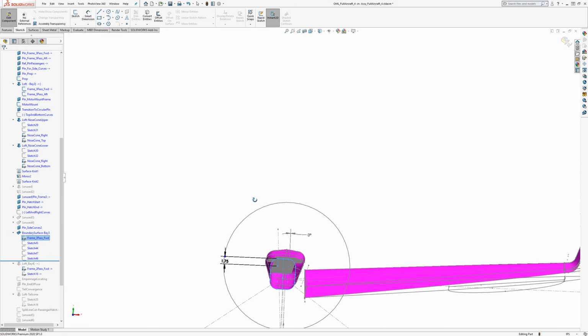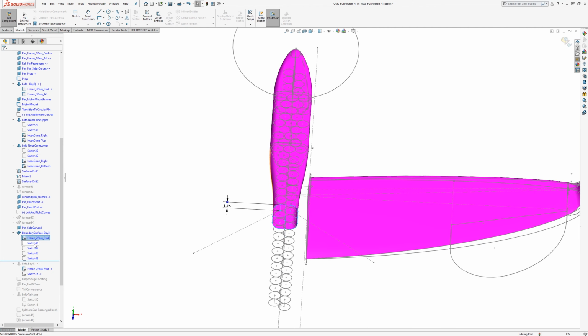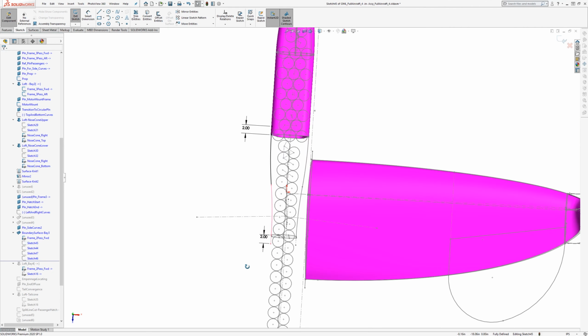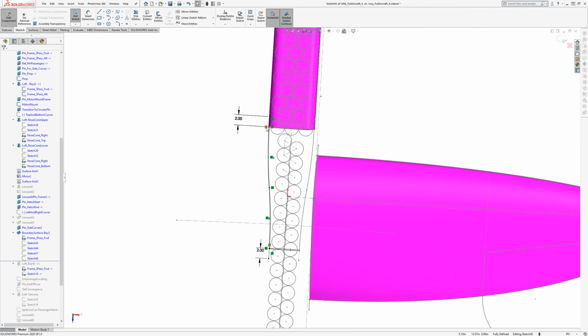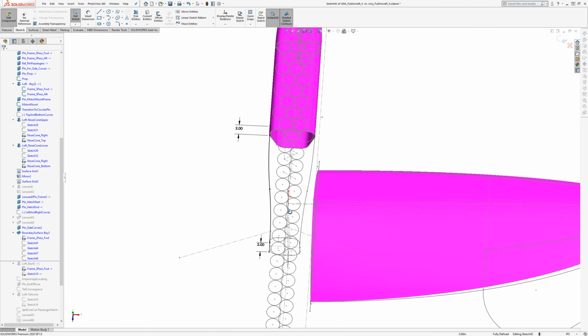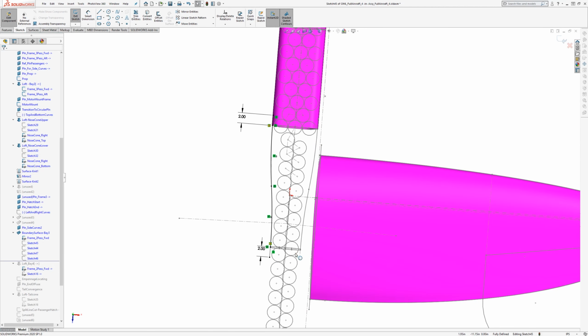So there's a two-passenger bay, and here are the ones that are used. Those are a tangent to the straight part of the fuselage and a tangent to the straight part of the fuselage after it, and then two tangent lines that are forced to be equal length. I find that makes it a pretty smooth transition. So I wanted it to slowly get narrower over where the wing is starting to come in, and this leaves a lot of room for structure and things on either side here.